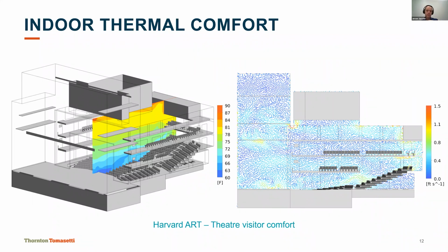So the fresh air comes in through a labyrinth below the ground floor. It's been sucked in through openings in the ground and below the seating, and it's been sucked out naturally through two chimneys, two wind catchers at the top. And the question here actually was, when there's a play happening, so you have a full capacity of 200 people,